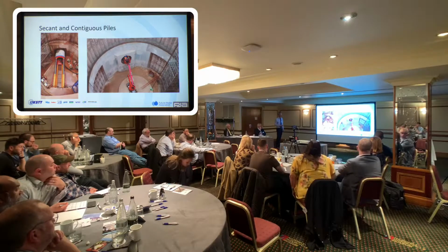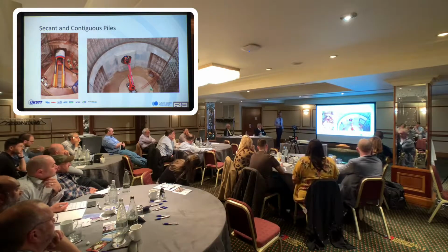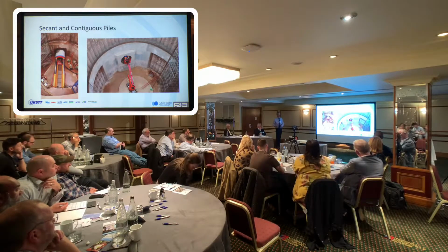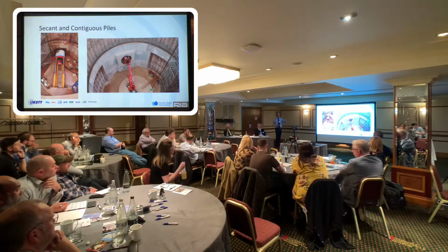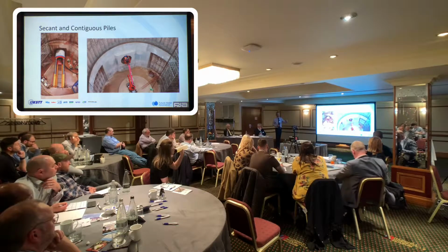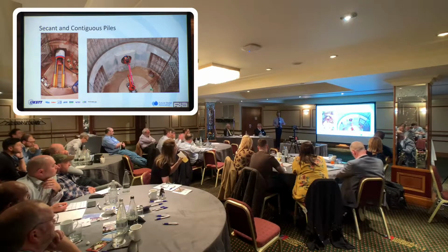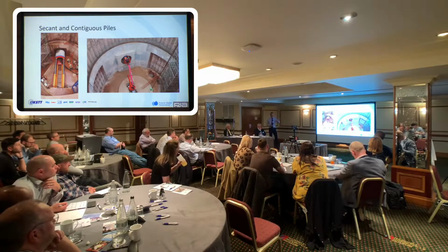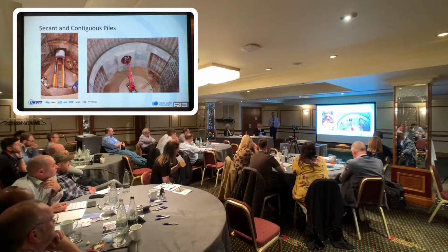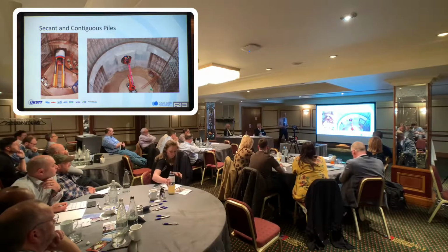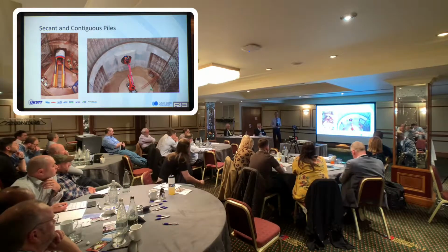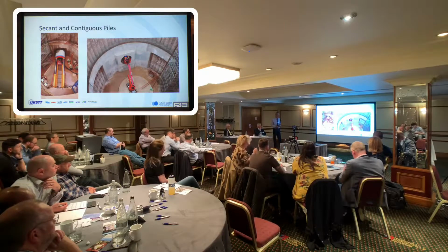And one of the problems with the gypsum is when you first excavate a shaft in this material, you might get a little bit of weeping through the gypsum. But as that water continues to flow, it erodes the gypsum and the flow gets quicker, and then the gypsum erodes quicker and then the flow gets quicker, and unless you're very, very quick, you can get into a lot of trouble with groundwater control.